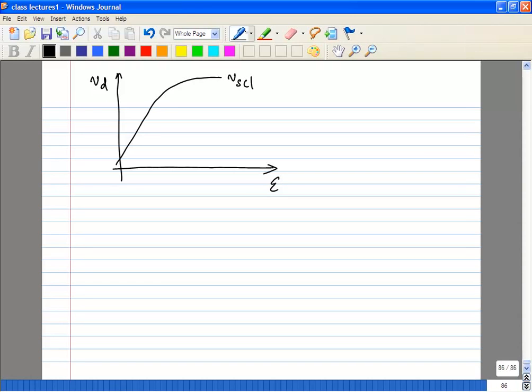Okay, so your scattering limited velocity is mu n times EC. Some people use ESAT. So we'll look at it next. We'll look at why we are interested in this short channel. In reality, even though it happens only at very high electric fields, you're trying to keep the electric fields constant. The actual short channel effects do not depend exactly on the length of the device. They actually depend on a ratio of parameters. So we'll look at what ratio of parameters they depend on.